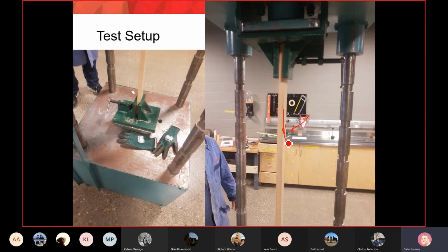That's why we use wood. If we use steel, once the column buckles, it will be permanent, and we simply have to throw it away and use more columns, which is expensive. So that's why we use wood columns or wood studs.